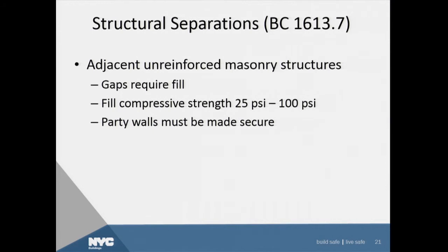While it definitely is undesirable and an unintended consequence, the intent here is to fill the gap with something that has some rigidity. You see stiffness values required here. This will hopefully keep the adjacent structure in its place, while maintaining the gap so that should that structure eventually be torn down and rebuilt, you can just remove the compressible fill material and rebuild a new structure.